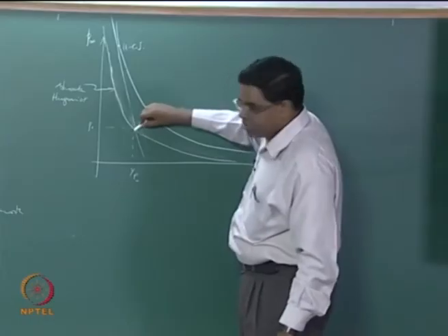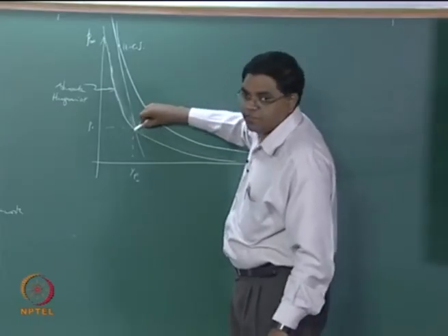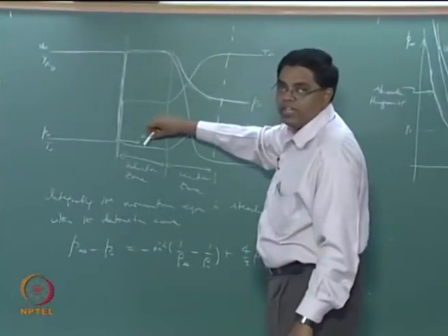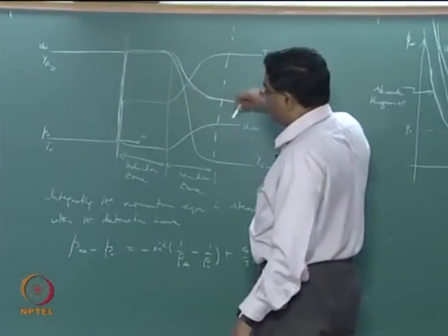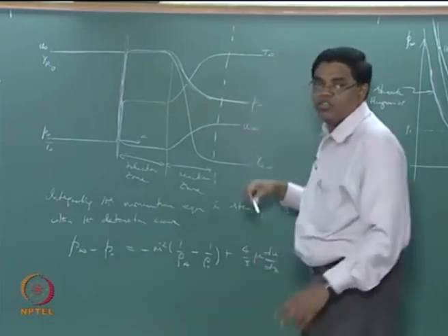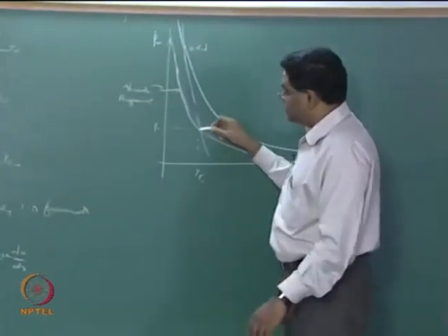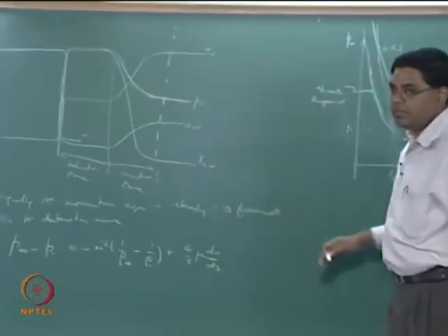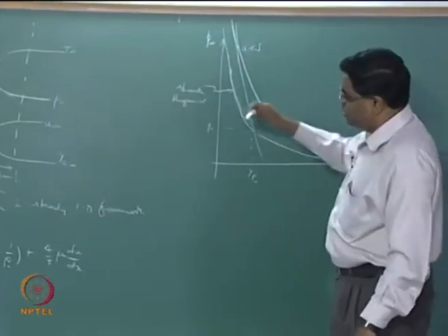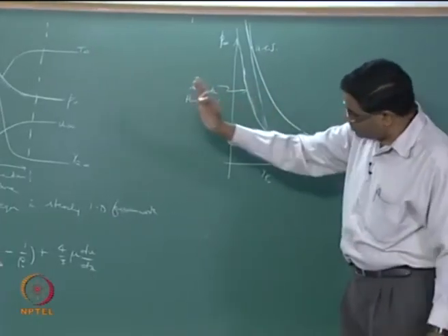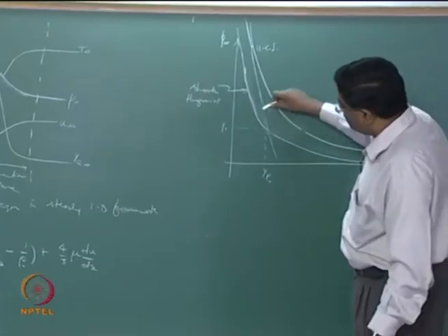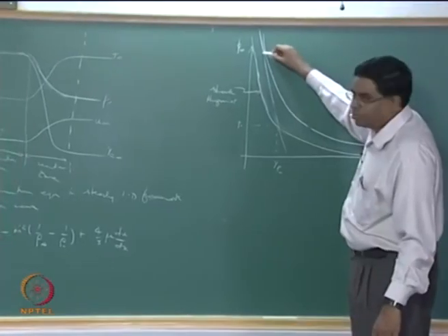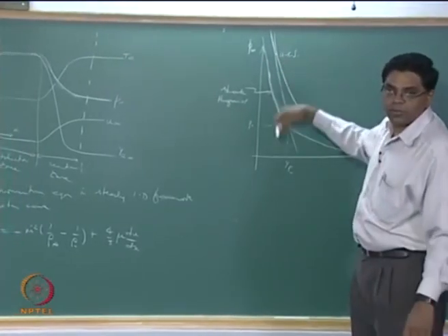So you start from here, right, that is for 0 du by dx, you go through a 0 du by dx again, and you go through a 0 du by dx again. So you go through this 3 times, once at the start, once at the end, and once somewhere in between. That means our system should lie on the original Rayleigh line 3 times, starting at this point, ending at this point, but also somewhere in between.